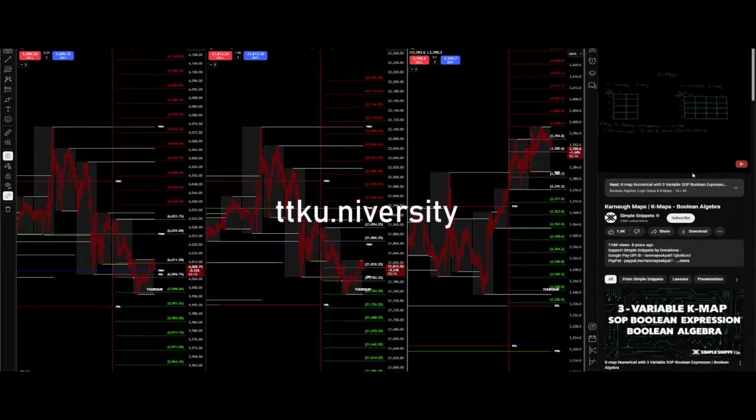Okay, so as you can see on the screen, I have drawn a 3 variable K-map and a 4 variable K-map. Here are the variables A, B and C for the 3 variable K-map. Now as you know, if there are 2 variables, we have 4 different values. So I have written them vertically, that is row wise. So 0 0, 0 1. Now instead of writing 1 0, the way we write it is that we write 1 1 first and then 1 0. For the variable C, we have only 2 values. So the columns form as 0 and 1.